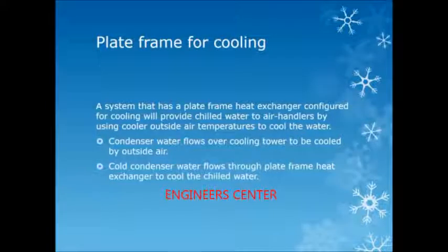It has a plate frame heat exchanger configured for cooling. It will provide chilled water to air handlers by using cooler outside air temperature to cool the water. The condenser water flows over the cooling tower to be cooled by outside air. That water is then flowed through the heat exchanger to help cool the chilled water.